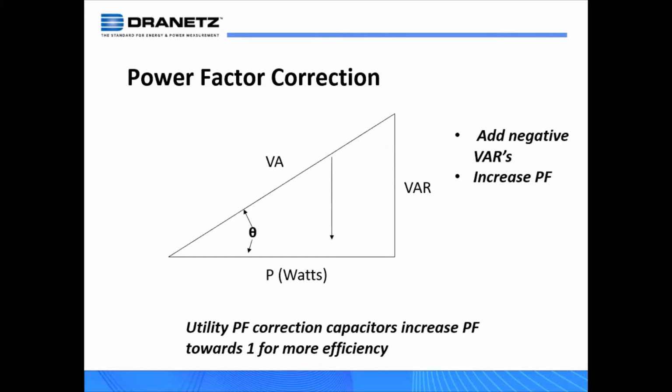Yeah, I would say that is correct, but it depends on how you're viewing power factor correction. There's basically two different ways of viewing it. From the end user perspective, you have to remember what capacitors do, right? They add VARs to the system. So you always have to keep in mind that you have to have a certain amount of VARs in the system in order for things like motors and transformers to operate. So you always have to keep that in mind.